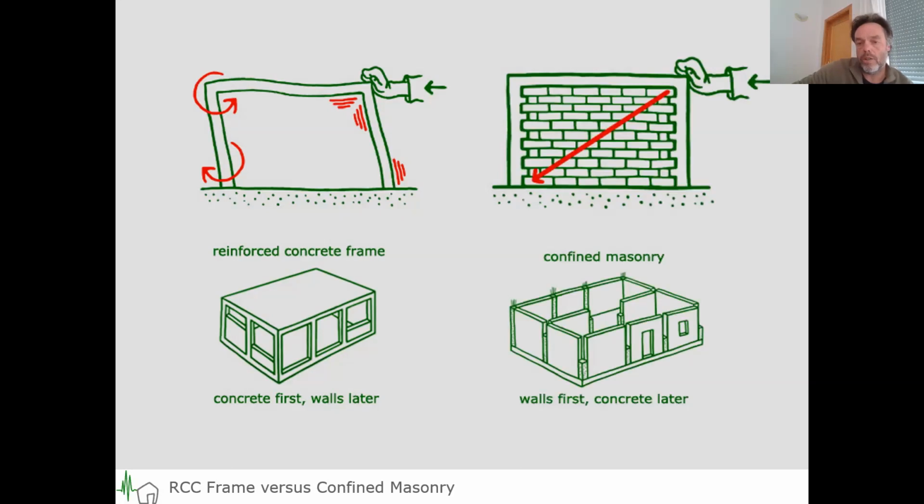So what we do is confined masonry. And that's the point I want to make now in just a few minutes. Confined masonry, that really works. And it works the other way around. You build your walls first, and then you cast your frame around it.